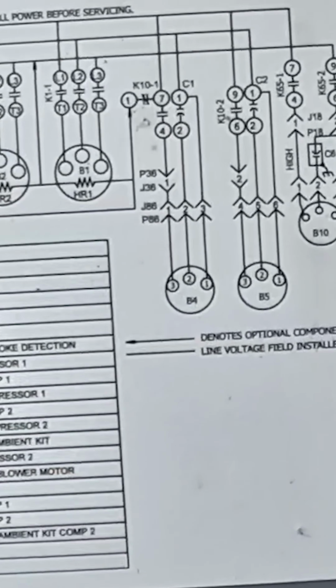So yeah, I'm just striking out for accuracy on this. And on most of these, they're going to show you notes. They'll be labeled in triangles. Right there, there's a triangle. J261, that's going to be a junction. P251 is a plug. So anywhere you've got a junction, you can have a plug. Like right here. One side will be labeled a J, one side will be labeled a P. But let's see what note number 5 is on this one.